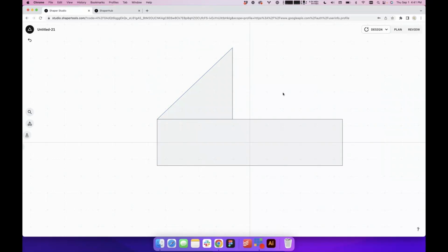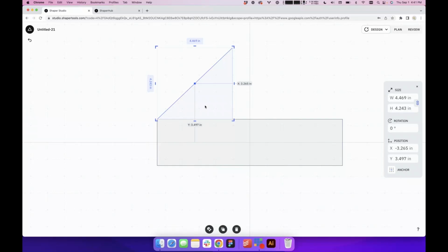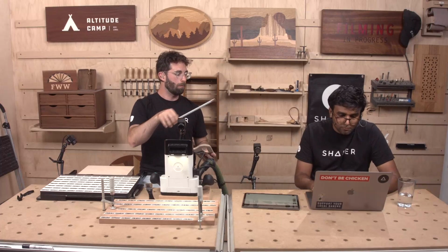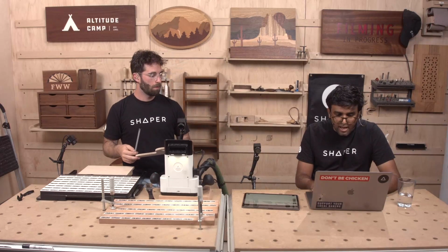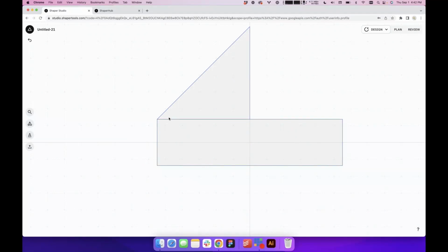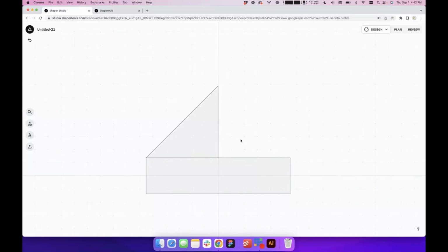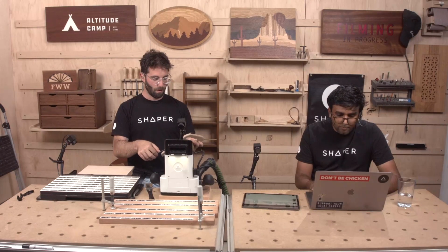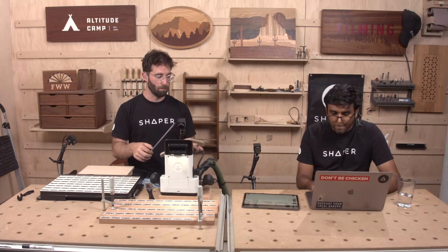That's getting there. It should be about 5.5 inches wide. Okay. And about 4.5 inches tall with the round. So let's leave it square, like 5.5 inches wide and 5.5 inches tall with that corner, and then we'll round off that corner. Okay, and I'm just snapping this to the top left corner. There we go. Now we want to round that top corner. We want to round this off. Let's make a little circle. And that's about 2.5 inches in diameter.